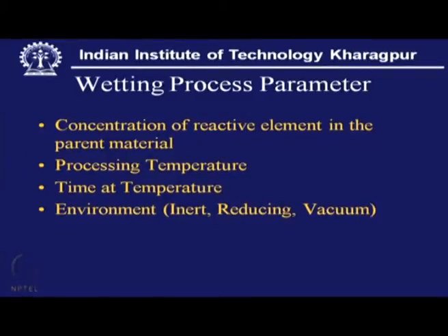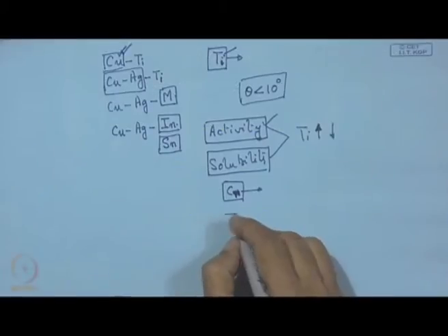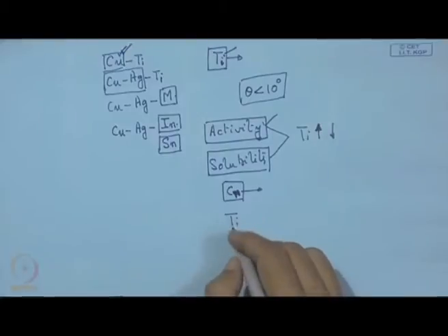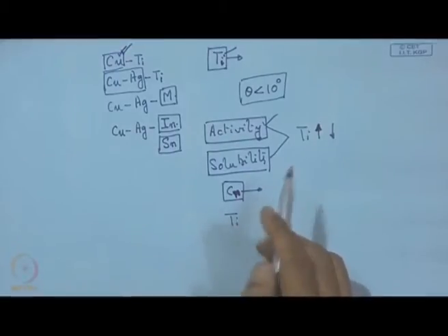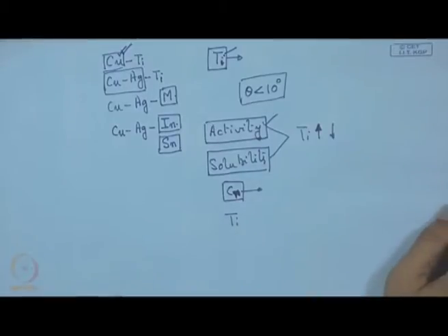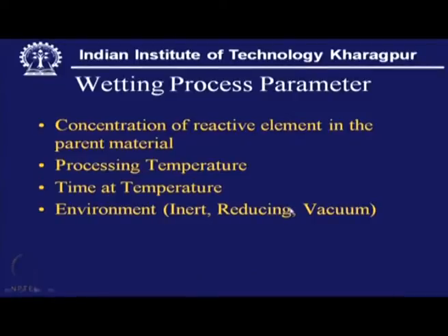But when the activator is titanium or a similar material from group 4, we know that a reducing atmosphere by passing a stream of hydrogen is not desirable, because hydride of titanium will form readily.